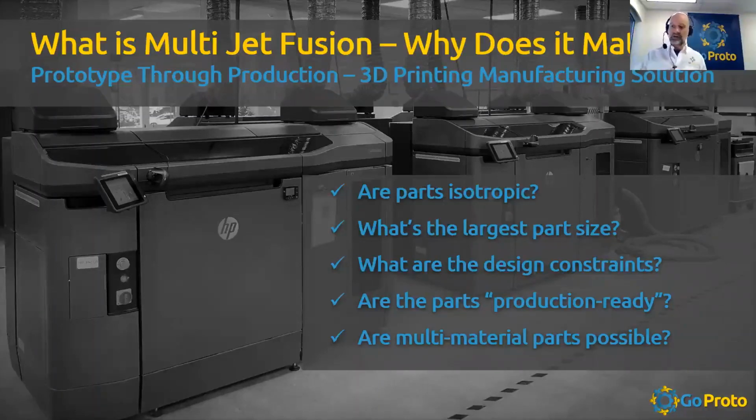So an exciting thing about HP is you get complete fusing between those layers. So they are much more what's called isotropic. They will perform the same or very similar in the Z as they do in the X and Y in most properties. So that's a very important thing to be able to use this process for production. So that's an important property to be able to talk about.